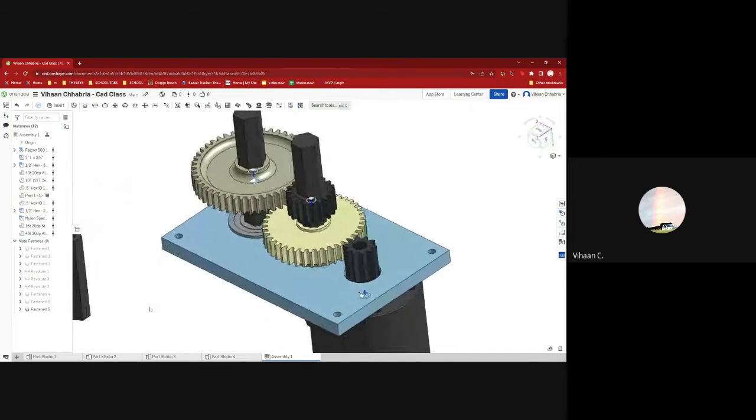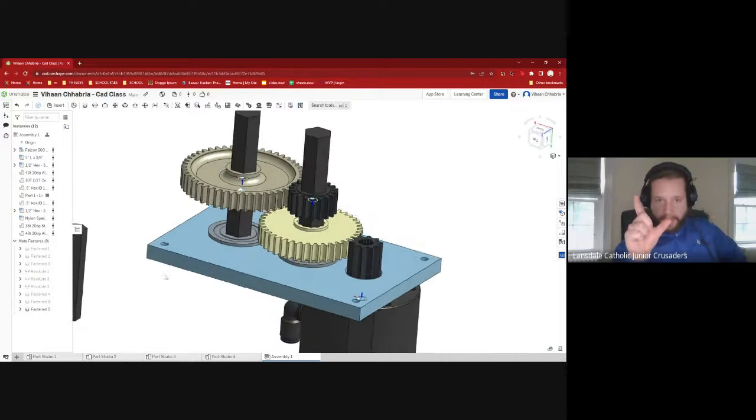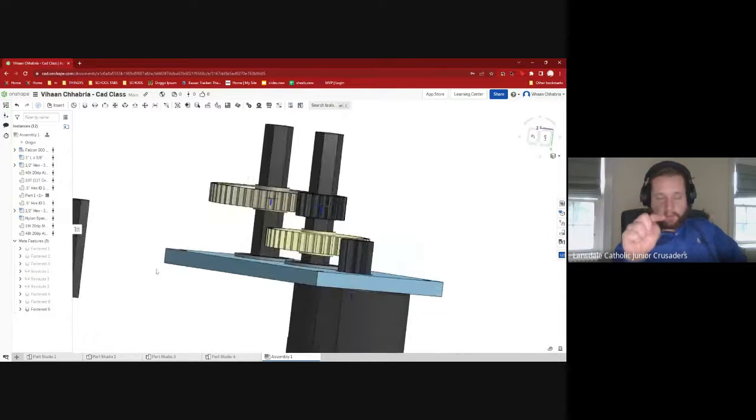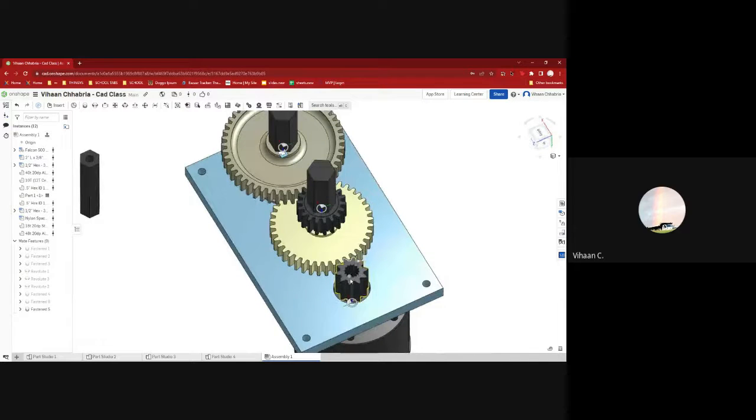Oh, no. So the holes for motor mounting, it's a 2-inch hole pattern. In other words, from the center of the gearbox, it's 1 inch to one hole in one direction, and then another inch in the opposite direction from the center of the motor. Okay. So from like here, from the middle of there, 1 inch there.